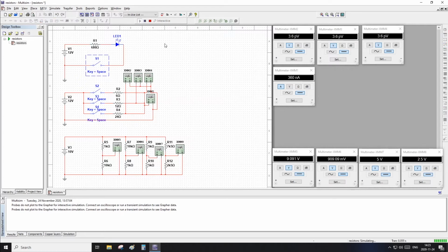So if we start a simulation, and we switch it on and off, that's all fine and dandy. Here we can see a setup for the same system: a 12 volt power supply, a switch, a resistor, and eventually going into multimeter 1, that's this one, and we will measure the amps running through the resistor next to ground.